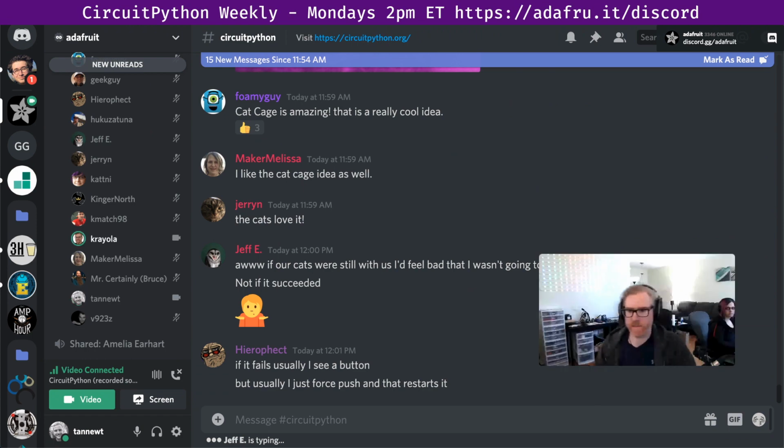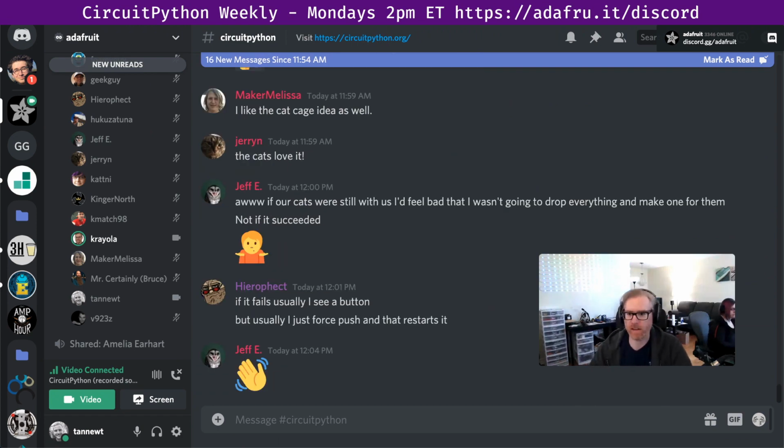So it's been a while since I joined the weekly. I've been busy working on LED animations and pushed a fix a week ago for pixel buffs so that it behaves better with RGBW strips by allowing you to assign 3-element or RGB values to an RGBW, and it just works. So that made the animations just work with RGBW strips.